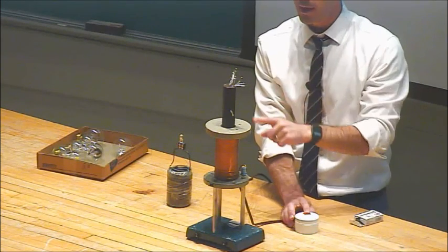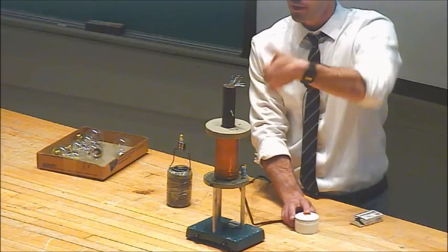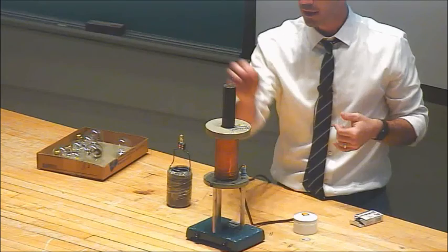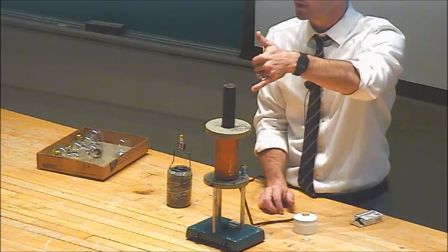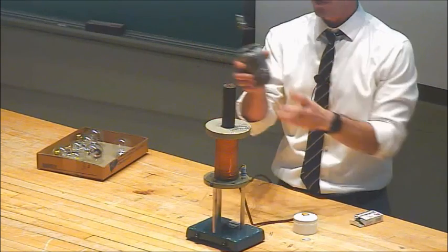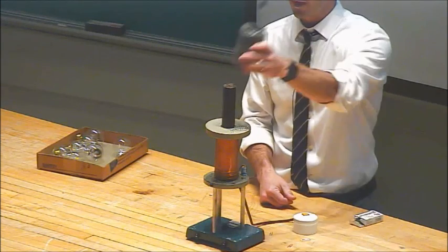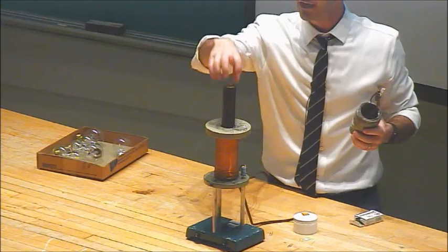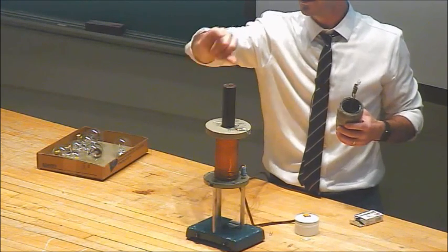But here's what's nice about that. This electromagnet is actually flipping north-south, north-south, north-south 60 times a second. Then I let go of the button and it's off. Okay. So this electromagnet is flipping north-south 60 times a second. Here's why that's nice. Here I have a light bulb connected to a coil of wire. If I were to put that near here, that's not going to do anything. But when I push this button, this magnetic field is alternating 60 times a second.